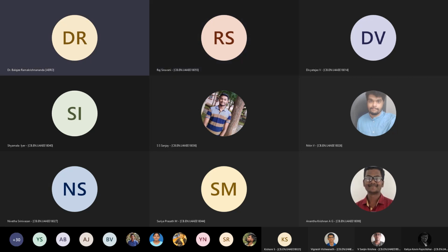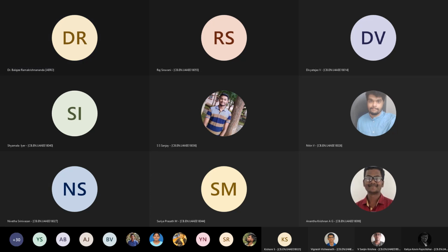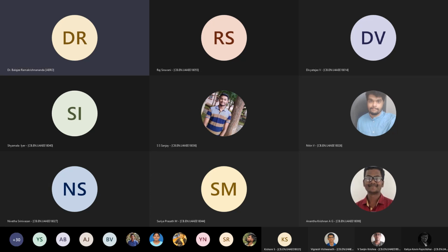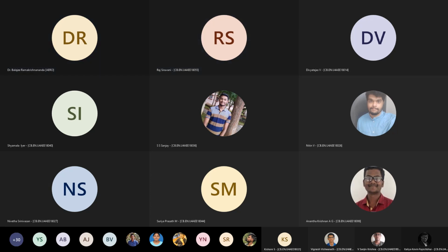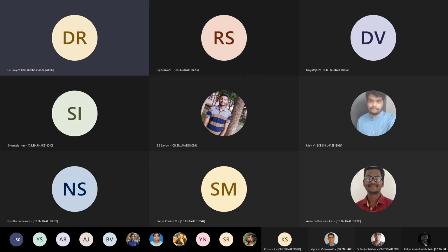So the range is actually cruise. Now he has given CD naught by 2K. Why? Root of CD naught by K is actually your optimum CL, correct? Yes, sir. Dividing by 1 by root 2, so that you give an allowance; you may not be flying at L by D max during cruise. At 0.94 L by D max is there, no? You'll be flying there at that point. You're assuming even worse, 1 by root 2 times that.